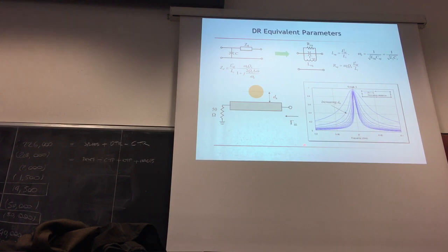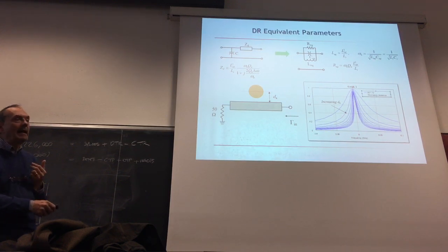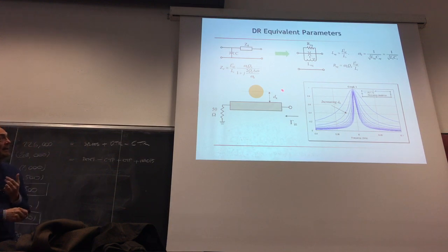But a very small displacement from these resonant frequencies is sufficient for the reflection coefficient to become very small. In fact, when the electric resonator is transparent, what remains is a transmission line closed on its characteristic impedance. So, without the resonator, we see gamma in quite close to 0.